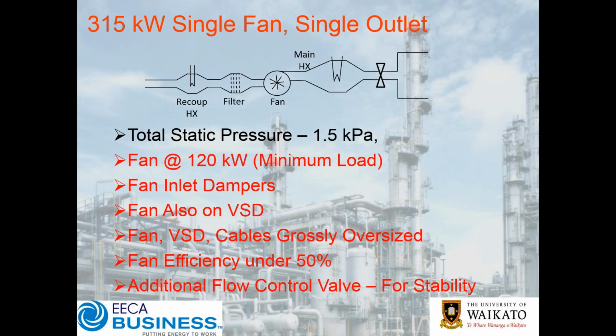So here's a simple application where we had a single fairly large fan with a single outlet. Now what was interesting with this particular system, we had a relatively modest total static pressure of 1.5 kPa. The fan was actually at virtually minimum load at only 120 kilowatts. We had inlet dampers as well. The fan was also on a VSD. Now obviously, this 315 kilowatt fan is fitted with a 315 kilowatt VSD, rather large cables and everything else.